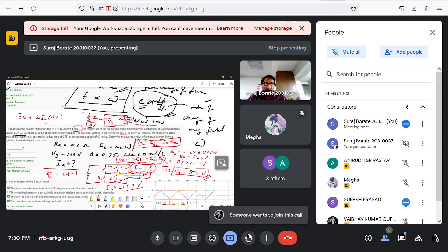Okay, and in the in runner type, let's say if this is the in runner type and we have the rotor here and we have the coils outside. Okay, the height of the motor and the diameter of the motor is enough for us to tell whether the motor is a high torque motor or high speed motor or something like that.